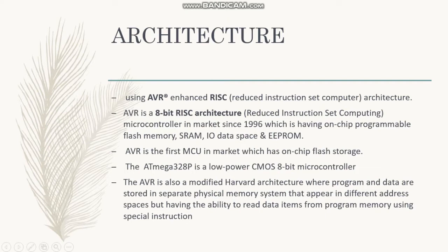The AVR is also a modified Harvard architecture where program and data are stored in separate physical memory systems that appear in different address spaces, but having the ability to read data items from program memory using a special instruction.